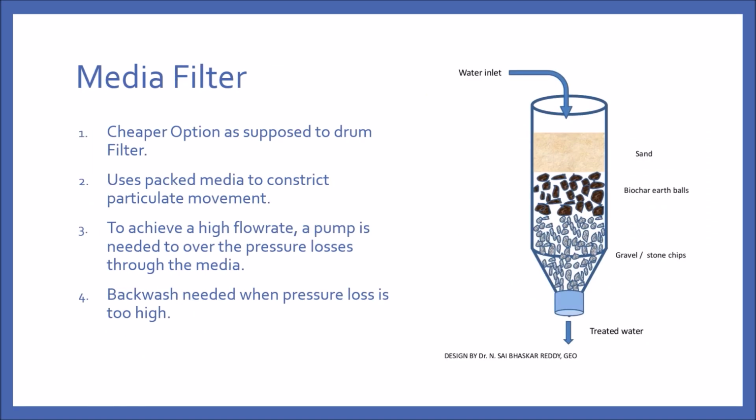We will now move on to the next part, which is utilizing media filters for suspended solid treatment. Number one, it is definitely cheaper as opposed to a drum filter. And the theory of operation is relatively simple, in which you pass the water through a packed bed media, which can be filled with sand. The way you distribute the sand can be done in different manners.